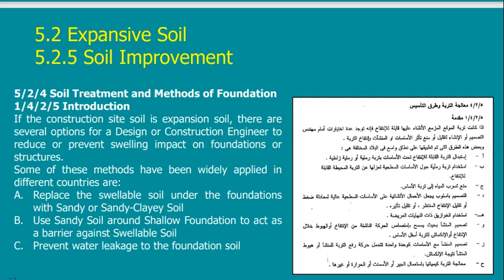So here, as we said, in some cases where we are going to use replacement, it does not mean that we are going to replace the full depth of the problematic soil, the expansive soil. Maybe I would remove 2 or 3 meters.